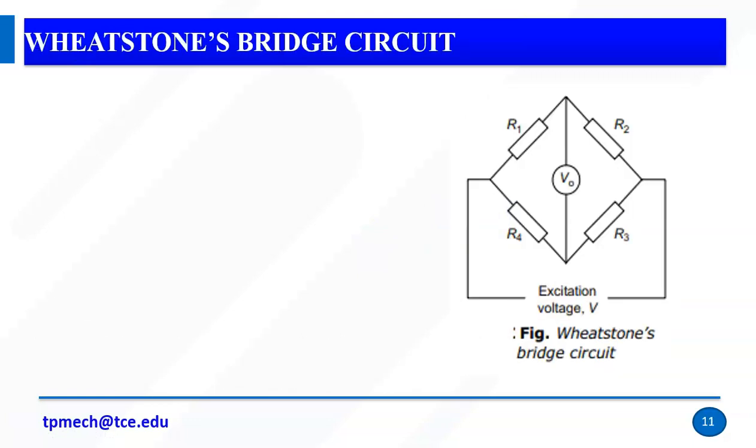So the second working principle is the Wheatstone bridge, right? This is the main working principle. Here we change the resistance and measure the strain. How do we get strain by changing resistance? It is like the previous gauge factor. If electricity passes, I get an output. The output changes because the resistance changes. The resistance changes because of strain.